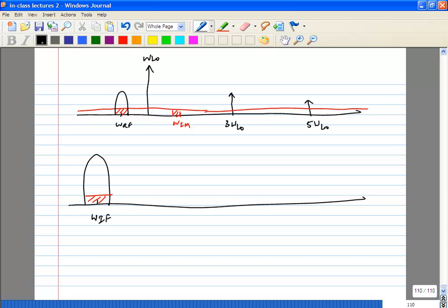So what's going to happen is, if you have some noise which is omega IF away from 3 omega LO, that is also going to get down converted to IF, right? So this frequency is omega IF. This component is going to mix with that noise to down convert it to IF, and same thing with these two guys.